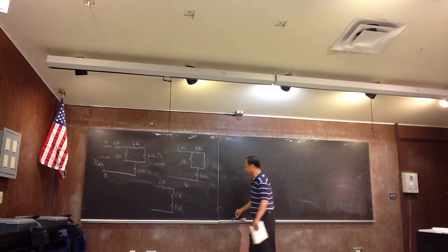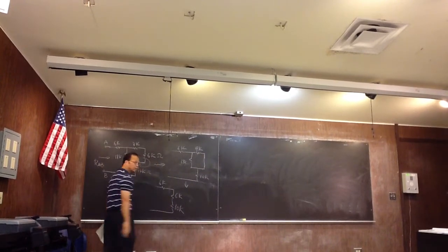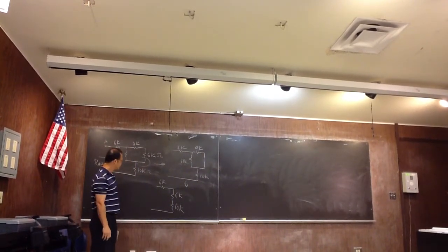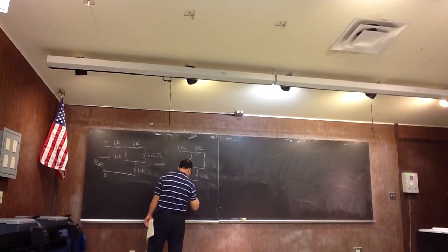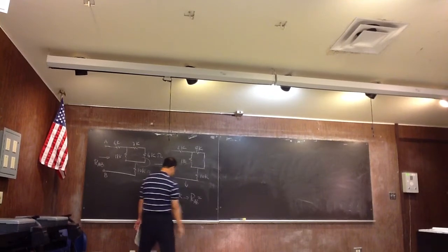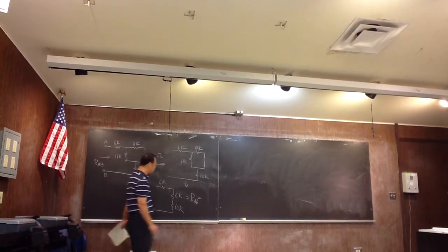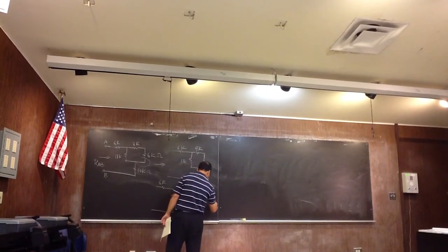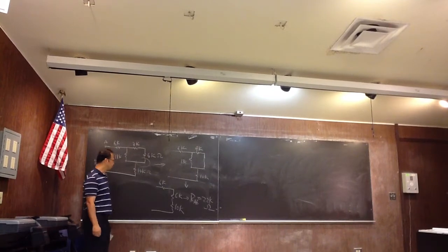All right. So now we have all three in series. So therefore, the final equivalent resistance is what? It's just the sum of the three. So 12K and 10K, 22K. 22K ohm. So that's the answer.